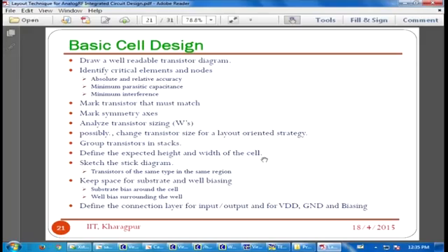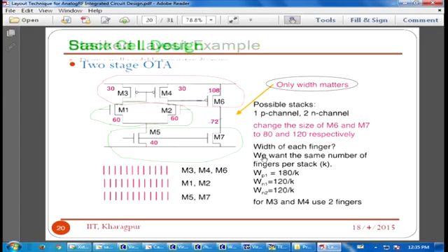Once you know the actual reason for doing this, it will be much easier rather than going through 1, 2, 3, 4, 5, 6 like this. So try to understand philosophically what is actually going on inside the chip. You are placing the transistors in such a way that while they are interconnected, they are compensating each other's deviations to give a uniform value. Clear? So that's the meaning of meaningful routing and placement.